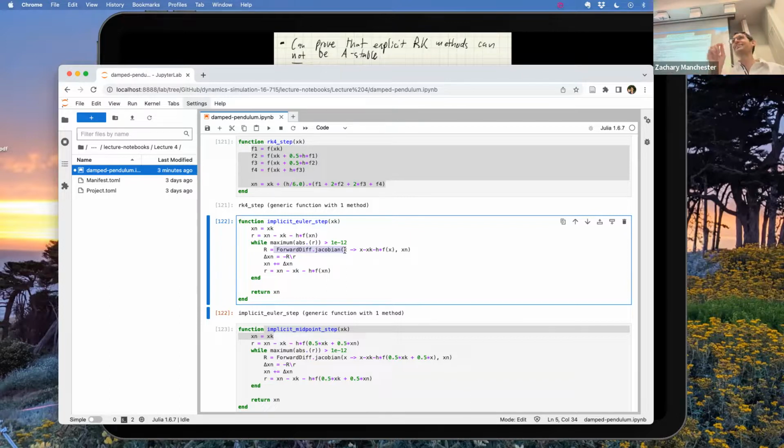So it depends, but that fixed point iteration only converges on stable, nice dynamic problems, right? For really gnarly problems, stiff problems, you have to do this Newton type thing, in which case it's just more expensive, right? But it lets you take big steps. So because of the ability to take big steps, on a problem that's stiff, this is absolutely going to win, right? Like I can take 10 Hz steps on this just fine.